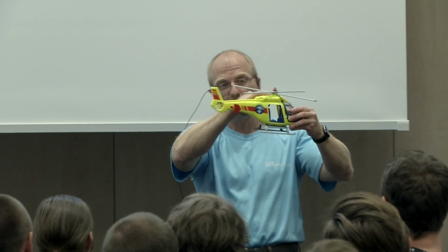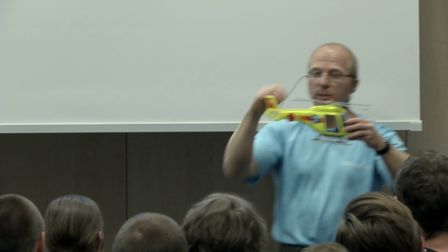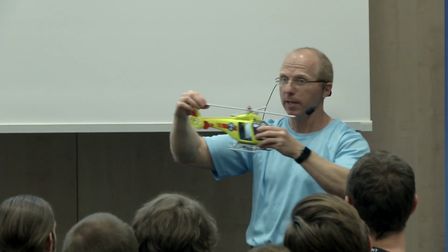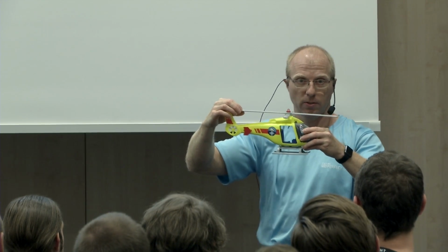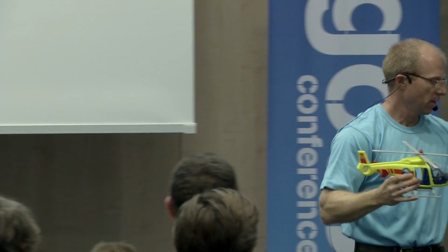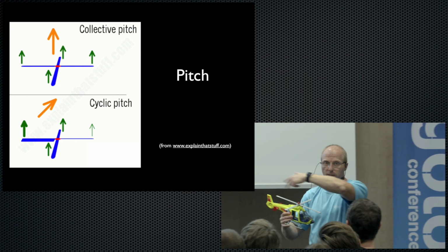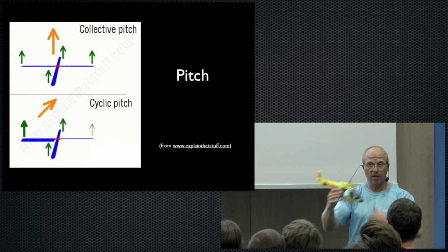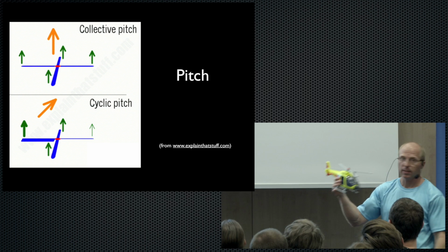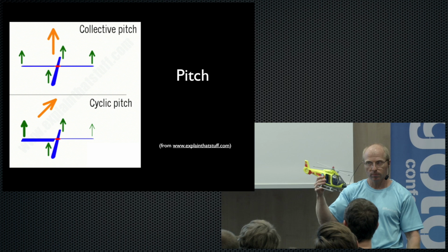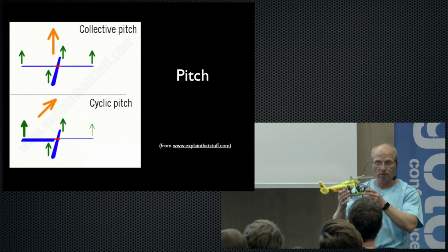It has a little gizmo here under it, and every time a blade passes by, the tilting of that blade is changed. So that means that the updraft on the circle is not equally distributed when we want to fly in some direction. We call this a cyclic pitch. So we are pitching, and that can be collective or cyclic.